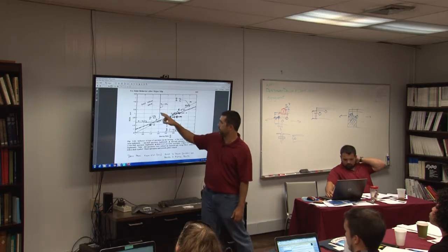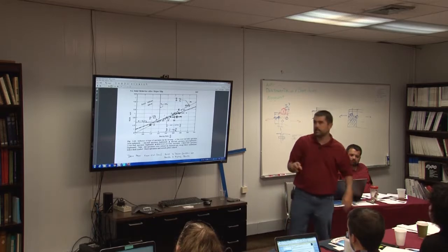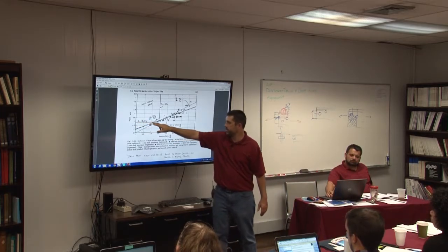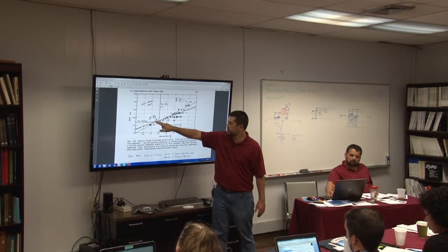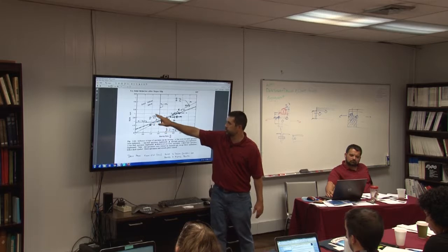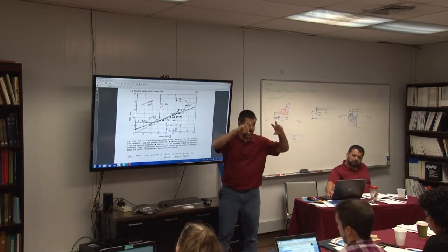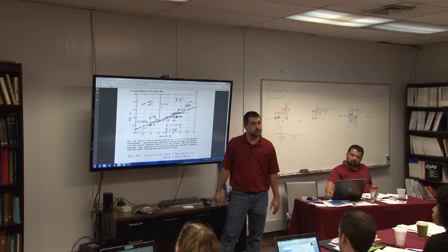What I will also show here is the design space that we design to in ASCE, where my 1.3 is my limiting bottom end distance. This is the section that's controlled by that 1.2 equation, and then my bearing capacity is limited by 1.5 times F sub u.